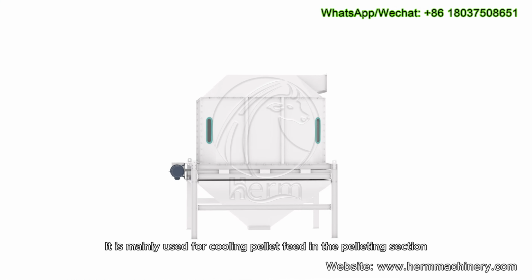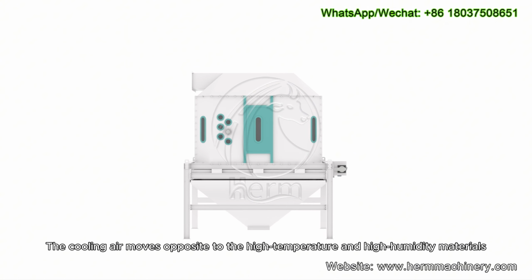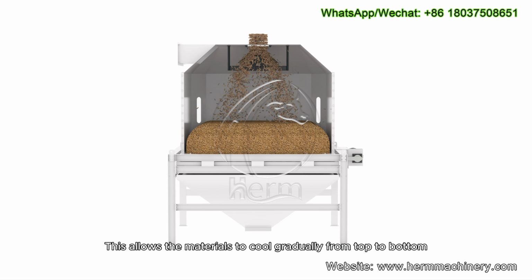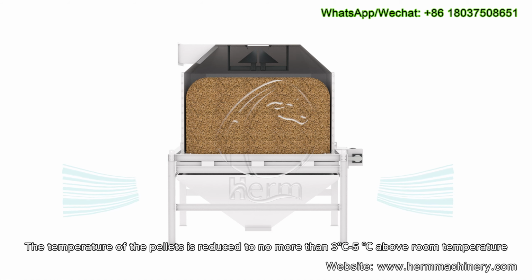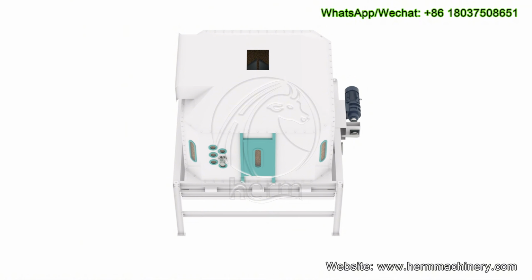It is mainly used for cooling pellet feed in the pelleting section. The cooling air moves opposite to the high temperature and high humidity materials. This allows the materials to cool gradually from top to bottom. The temperature of the pellets is reduced to no more than 3 to 5 degrees Celsius above room temperature. The moisture content is also safely reduced.